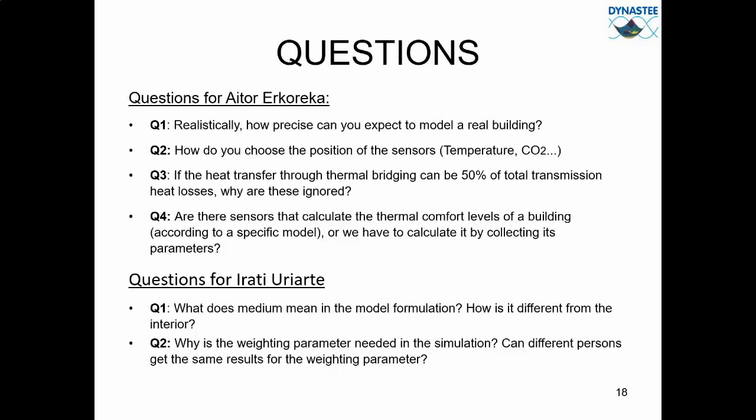And then it's more complex for the sensors measuring comfort parameters in the interior thermal zones of buildings, such as temperature, relative humidity, CO2 concentrations. And for those types of sensors, you have to install them in a representative place of the thermal zone you want to measure. Of course, the bigger the thermal zone, the harder it is to find a place where you get a representative value of the temperature, CO2 concentration, and relative humidity of the thermal zone.